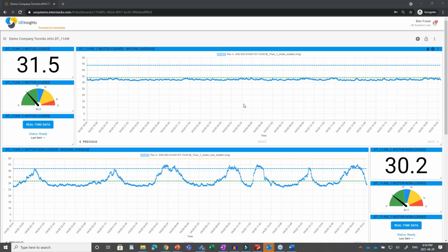So that 8, 16, and 35 is merely a guiding point for us. What we can see is we might set our first lubrication limits to make sure we cover the entire operating speed or loads of that bearing itself, because what we don't want to do is set it so it only needs lubrication when it's high, and that asset only operates in low speed for a month, right? And it never crosses that threshold. So we may fine tune those limits a little bit, but this is a great example.